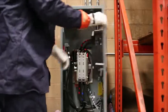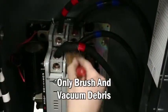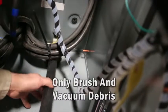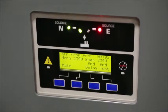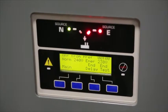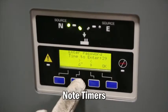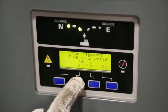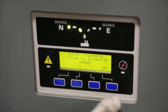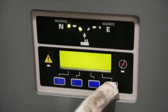Such technicians are found within a reputable distributor specializing in supplying and servicing standby generator systems. During an ATS planned maintenance service call, the technician will brush and vacuum any dirt or debris from inside and outside of the ATS, and never use compressed air to remove dirt or dust. Check the operation of the transfer switch before beginning service. Check timers controlling the time for transferring to the standby power supply and the time before returning power to the utility. This avoids several transfers when power is going on and off or only interrupted for a short period.